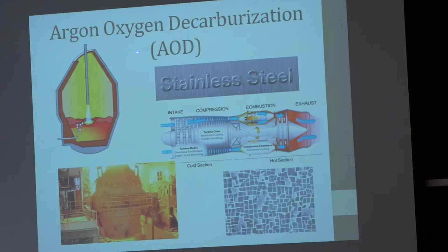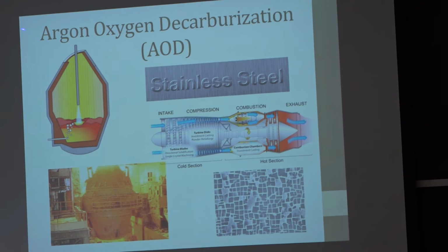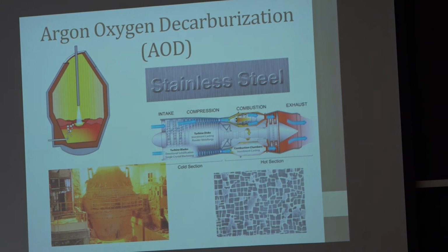They tried to use this to decarburize high-quality steel, and it's called argon oxygen decarburization, and you can get the carbon down to extremely low values, like 30 parts per million or less. In fact, you can get down to 5 parts per million with AOD. That's lower than you can get by just blowing air through. The equilibrium, thermodynamics, won't allow you to get lower. And today it is the way all stainless steel in the world is made. It probably dropped the price of stainless steel by a factor of 3 and improved the quality by a tremendous amount.